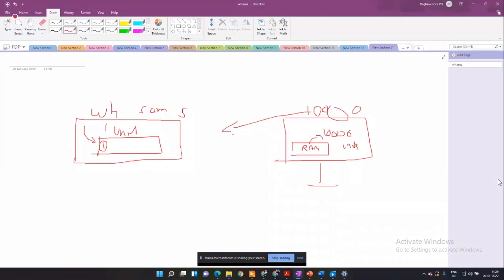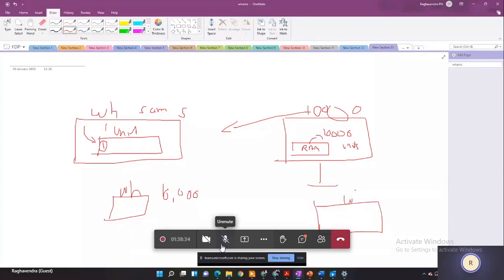Is this part clear? Even though the speeds in the FPGA and your system are different, because of the volume of data that we take for every iteration, we're able to make sure that, if a while loop on an FPGA runs 10,000 times, that's the same thing as a while loop in your host system running once. It can afford to be this slow. Any doubts up until this point? Please let me know.